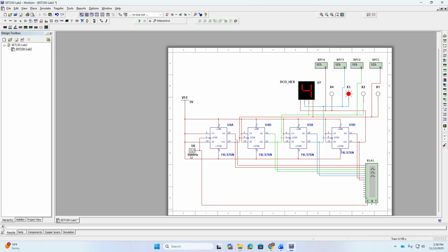Yeah, so if you can't tell, just go ahead and lower the frequency. But let me keep this at 1,000. And now let's look at what's happening at the actual frequencies of the output of each stage. So in this case, let's say we start off at 1,000 hertz. We should be dividing the frequency at the first 74LS76 flip-flop by 2. So we should be getting about 500 here. And then that feeds the next stage. So we should be getting about 250 there and so forth, 125.